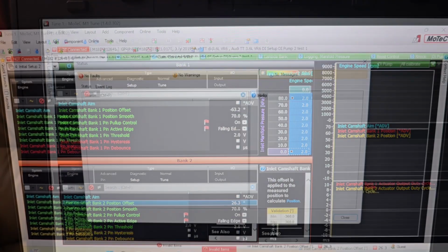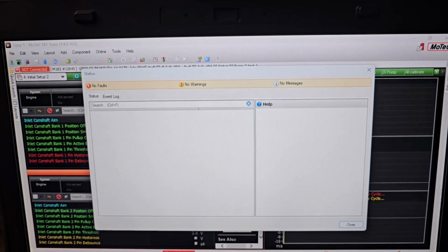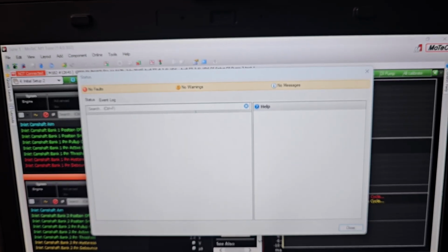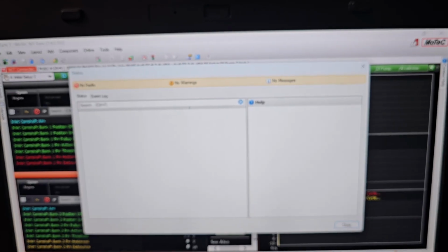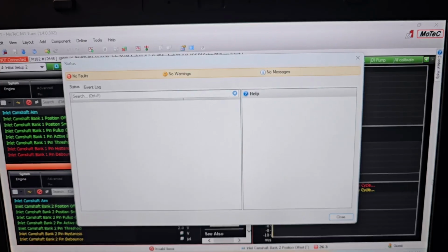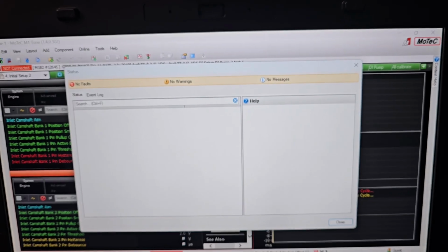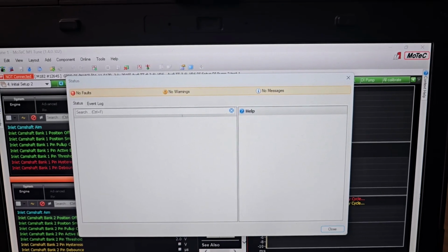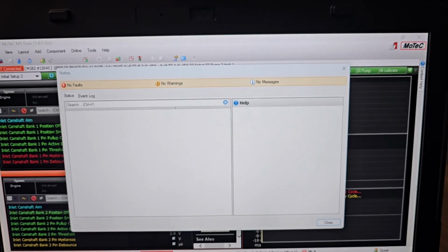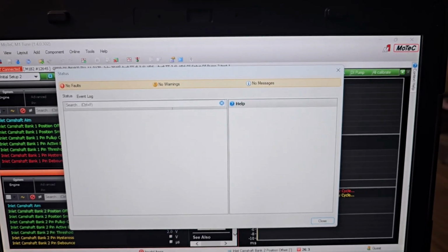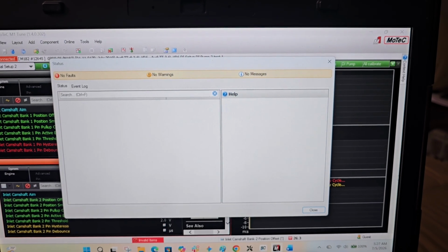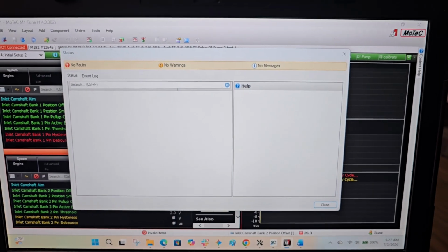Just to clarify a little better, Bank 1, I don't want to mess with that, because specifically for this package for Teddy's engine, Bank 1, we want to leave that set up as our default source and eliminate Bank 2. So in Motec's architecture, Bank 1 is always the primary default bank for any single cylinder head configuration or inline staggered setups like our VR6 engine. The ECU relies on Bank 1 for the core engine speed synchronization, rev sync, and primary variable cam control logic.